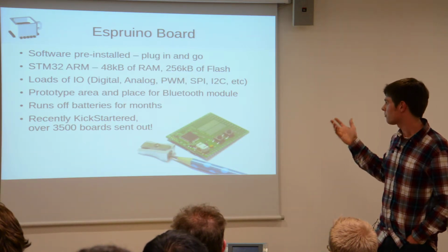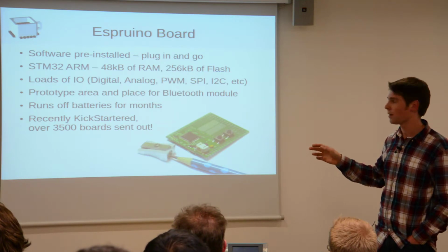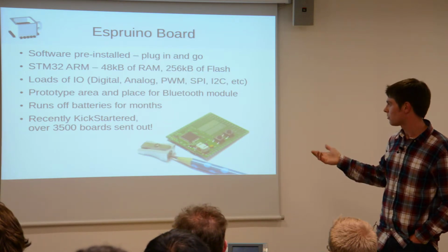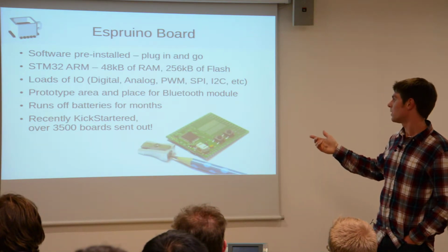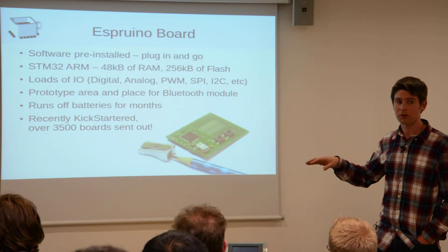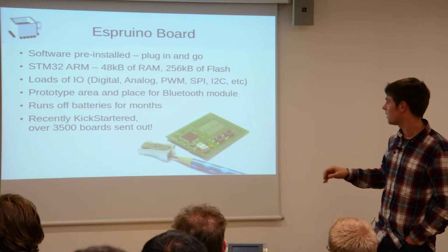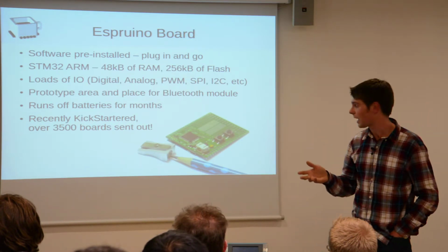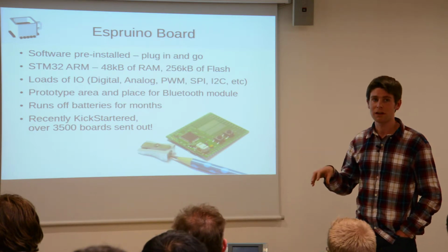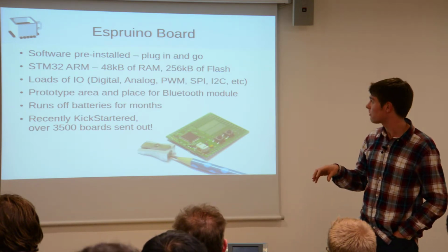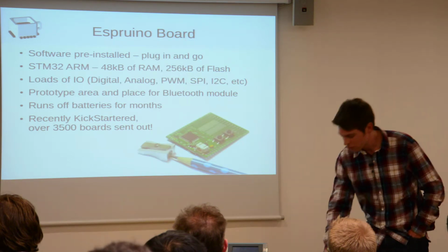And again, I've tried to think about the voltage regulator a bit. So in sleep, it'll draw about 110 microamps, and the new version will go down to about 50 microamps. I think I haven't tested that one yet. We're recently on Kickstarter, and we've got about 3,500 boards being sent out in January or February. So I'll try and give a quick demo.